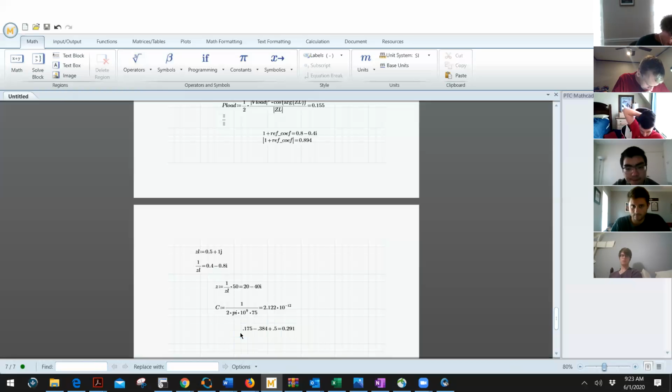So that means when I'm going to do this one, here's my load impedance. Now I'm going to move L equals 0.291 lambda. And at this point, I have a normalized admittance, not impedance, but my Yin would be equal to 1 plus j1.5.